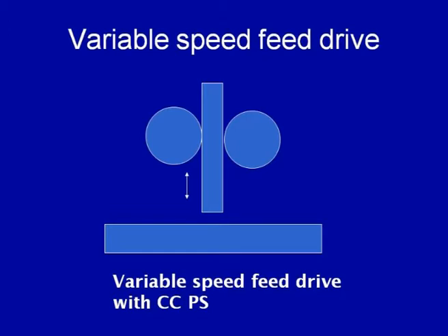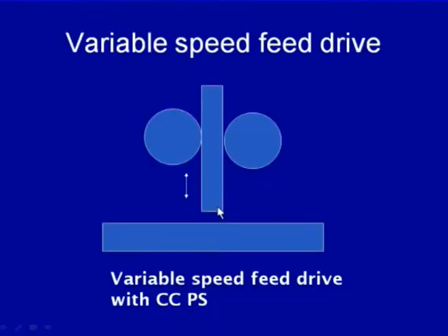So, the variation in current does not affect the melting rate as significantly as in the case of a small diameter and high resistivity materials, and in this case the melting rate is primarily governed by the first factor, that is AI of the melting rate equation, instead of the second factor where BLI square was dominating in the earlier case. So, under these conditions, where change in welding current is not significantly affecting the melting rate, the arc length is maintained with the help of variable speed feed drive systems.